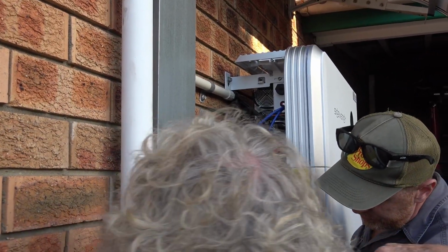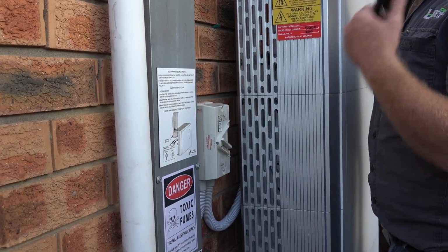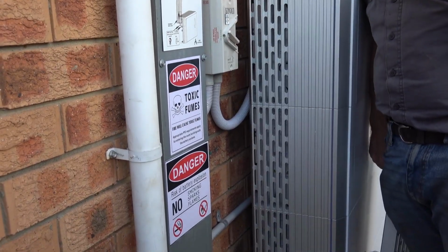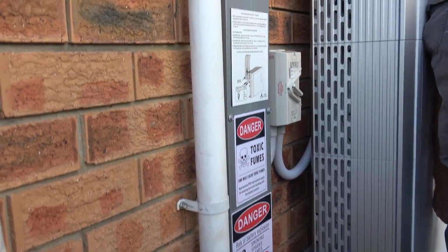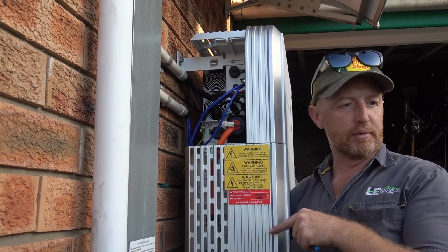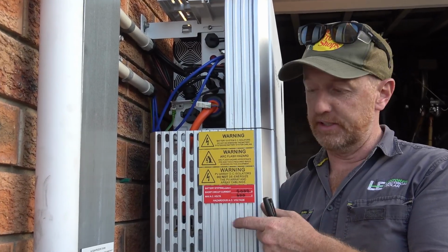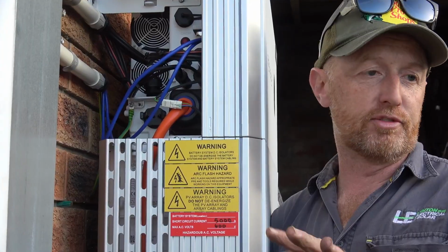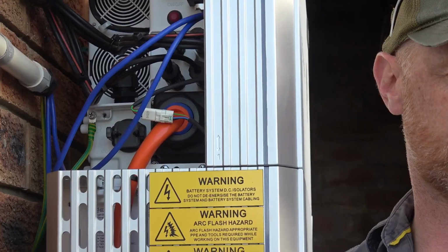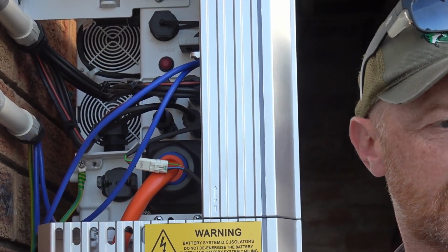If you read that, there's a full shutdown procedure if you were an electrician and you needed to work on something. But basically, if you need to turn off the power to the house, don't turn off the main switch because you go into backup mode. Turn off the one in the switchboard like you did normally, and that will kill the circuits. But it will still be live from here to there. Yeah, but all the circuits will be dead. So if you've got an electrician working on the house and he wants to turn off a circuit, that will kill all the power to the house.